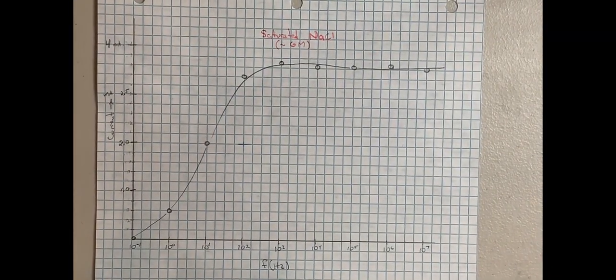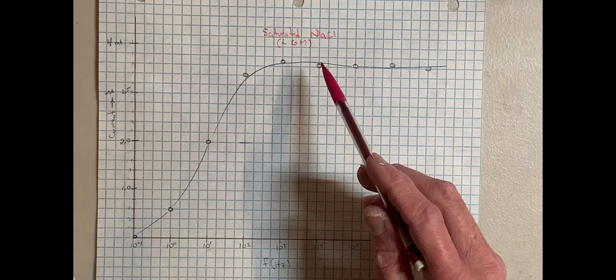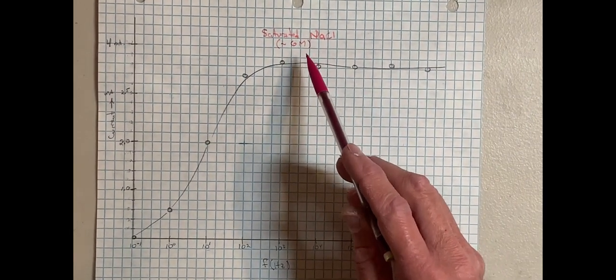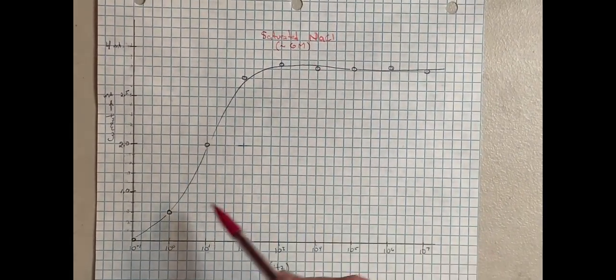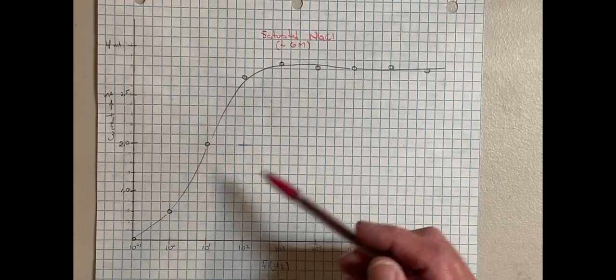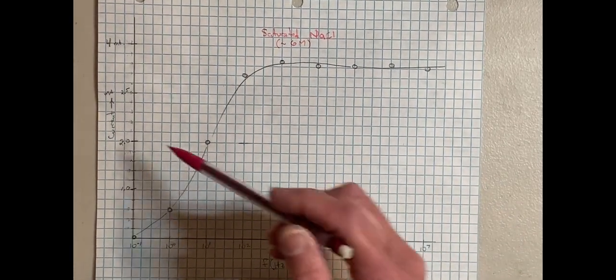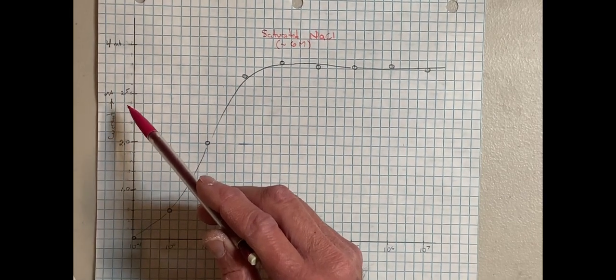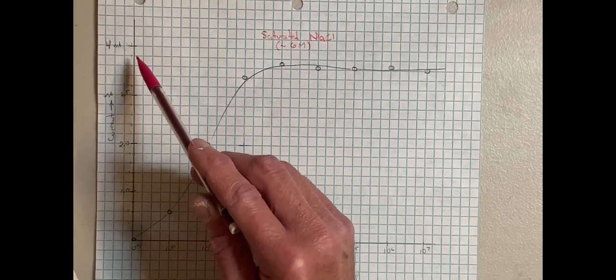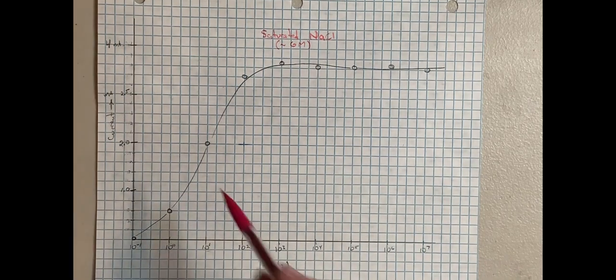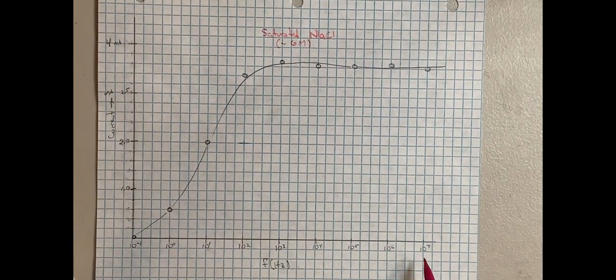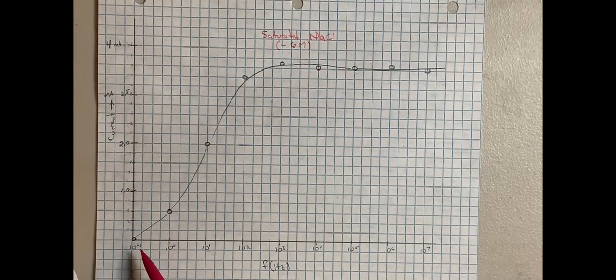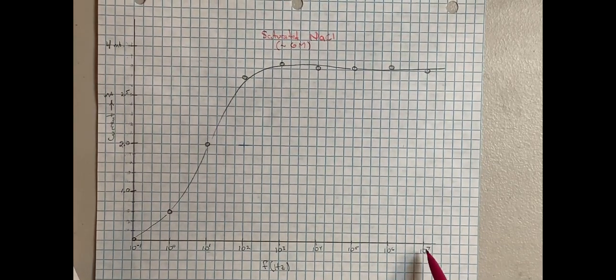So I took some current measurements with saturated sodium chloride solution, that's about 6 molar, while I varied the signal generator frequency. On this plot here, the vertical axis is current through the solutions. That's about 4 milliamps full scale on this chart. That's plotted as a function of the signal generator frequency, and that ranges from 1/10 of a hertz at the low end to 10 megahertz.